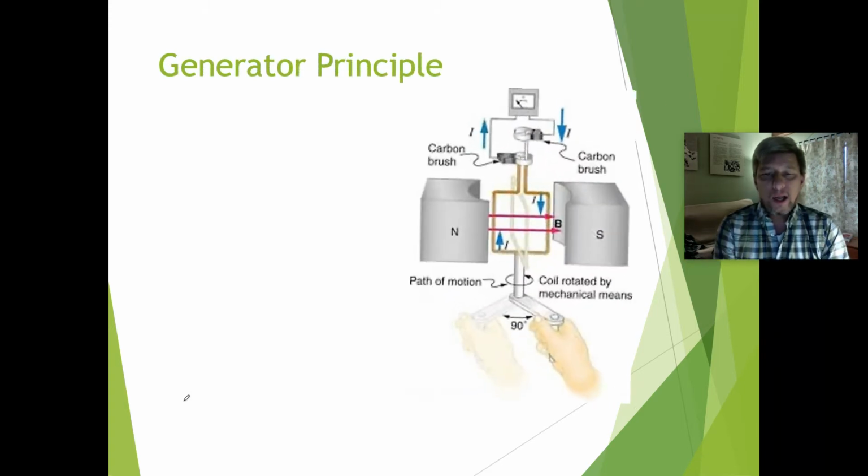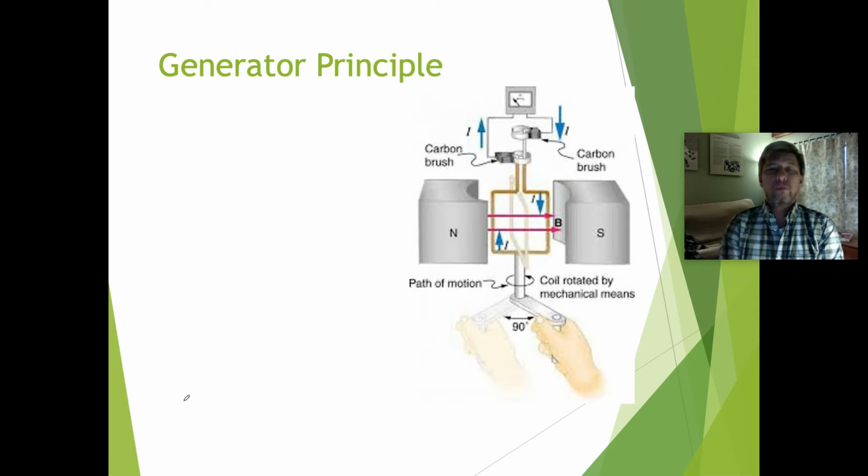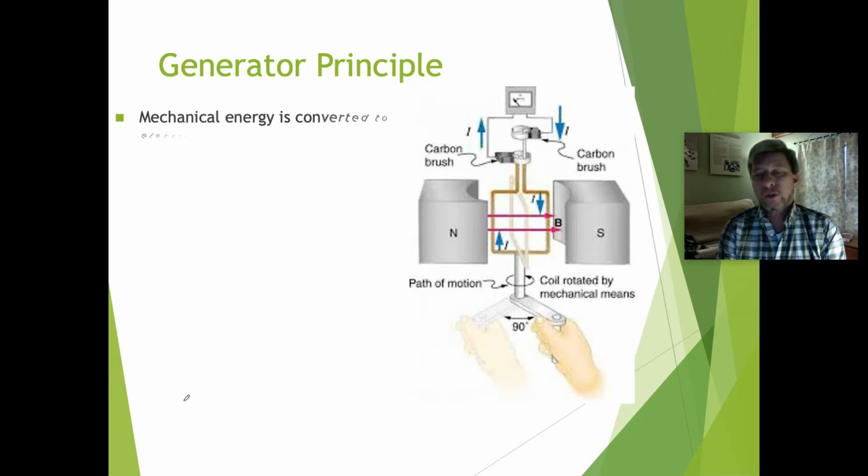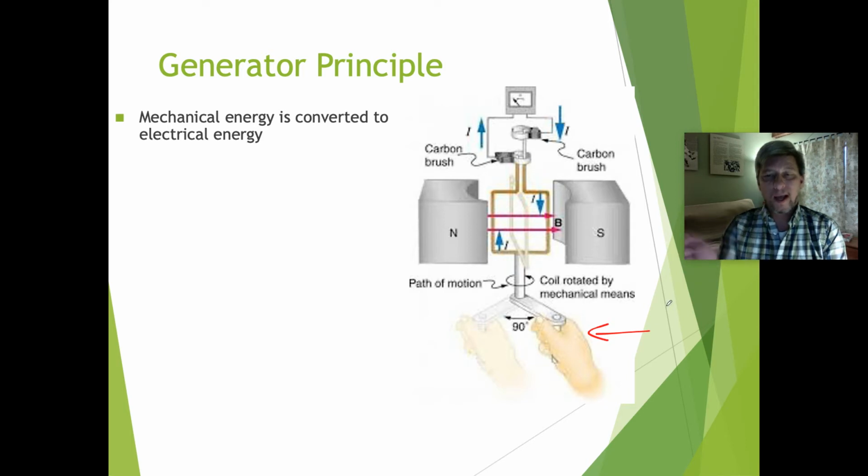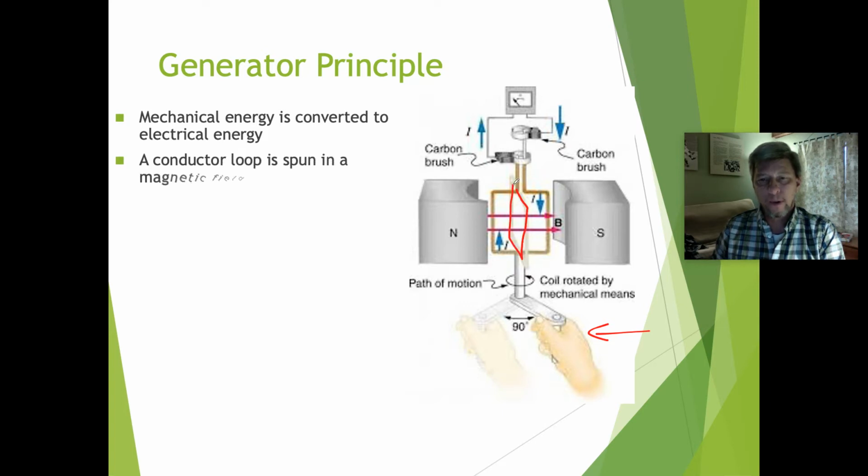What exactly is a generator? Well, we know that if you move a wire through a magnetic field, the electrons in that conducting wire will begin to migrate. They'll begin to move. And so if you look at the hand generator here, you see somebody's hand actually spinning a handle. And what that's doing is it's causing this coil of wire that you see here to spin. Notice it's shown in its perpendicular view here, as well as its parallel view here. And of course, we're sitting inside the field of a permanent magnet.